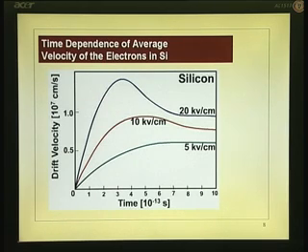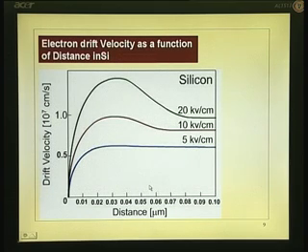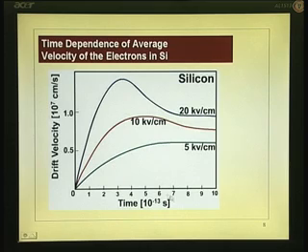You could have solved silicon with this velocity overshoot effect if it were retained for a long time, or a longer path distance. So, if you multiply this velocity by time, you find the distance over which the velocity overshoot effect is present in silicon, that is the curve. Notice here that these are 10 to the power minus 13 seconds.